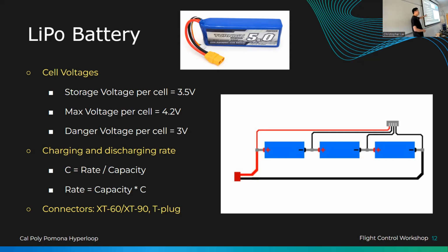Okay, so whenever you're using a LiPo battery, just be careful about the voltage. Every single time I use a LiPo battery, I have what's known as a voltage tester. While we're talking about safety here, by the way, we just need to make sure that we're very, very safe when using LiPo batteries. And this is an anti-flammable bag. So if a LiPo battery explodes inside this bag, we're good, because the fire will be contained inside.